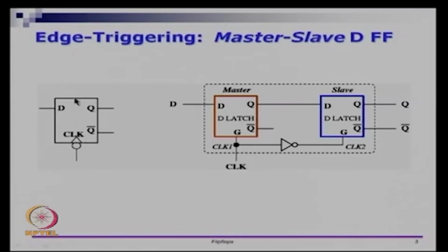If you see a rectangle with 3 pins for D, Q and Q bar and just a triangle-like thing, that is a positive edge triggered flip flop. In the positive edge triggered flip flop, D is sampled only when the clock rises. In the negative edge triggered flip flop, D is sampled when the CLK signal falls. Once you do this, CLK1, CLK2 and so on do not matter.